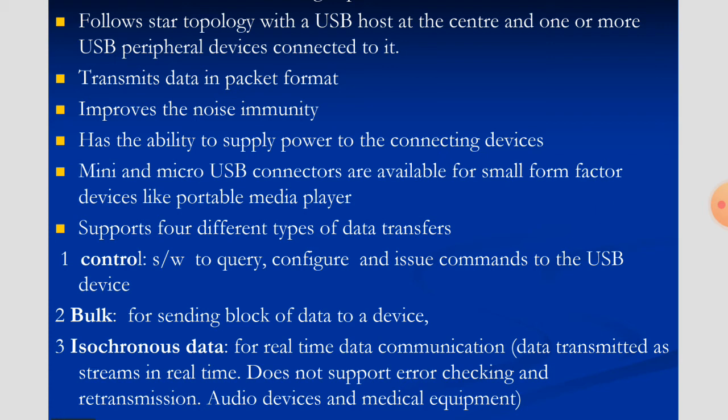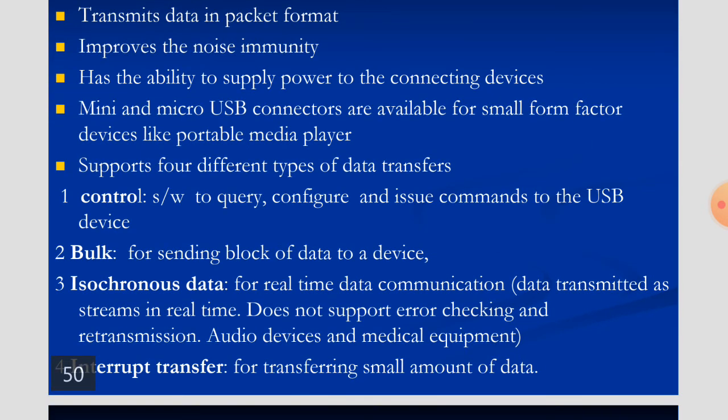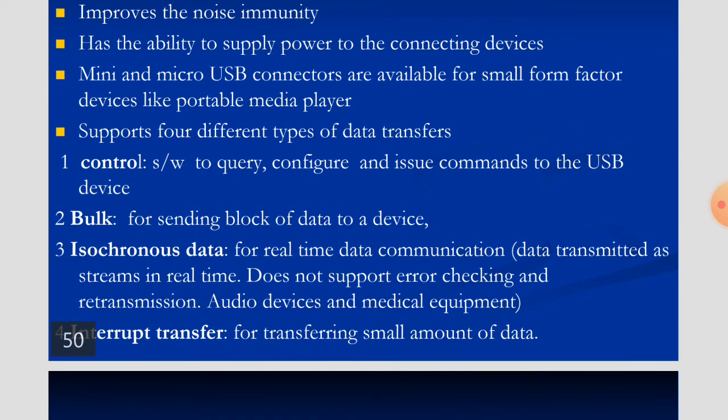And there are different types of USBs, mini USB and micro USB connectors are available. Depending on the application, you can use different types of USBs, and it supports 4 different types of data transfer. How are we going to transfer data? You can transfer data in the form of control, bulk, isochronous, and interrupt transfer. These are 4 different ways to transfer the data.